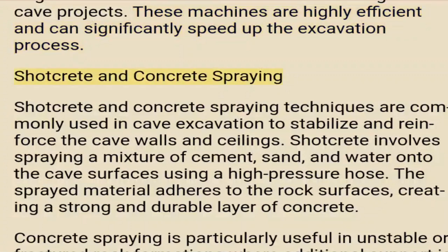Shotcrete and concrete spraying. Shotcrete and concrete spraying techniques are commonly used in cave excavation to stabilize and reinforce the cave walls and ceilings. Shotcrete involves spraying a mixture of cement, sand, and water onto the cave surfaces using a high-pressure hose. The sprayed material adheres to the rock surfaces, creating a strong and durable layer of concrete.